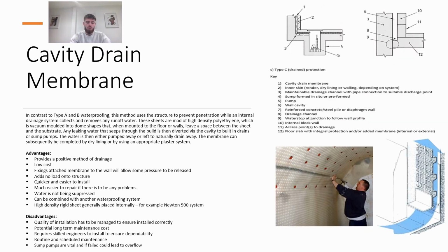Following my findings of all three types of basement waterproofing approaches, I've decided type A and type C will be incorporated in the design, as it provides the best waterproofing protection for varying risks and high water table, which type C is good for, and is the more durable waterproofing system. It is capable of withstanding significant head of water, and if any problems should occur, the systems are accessible for